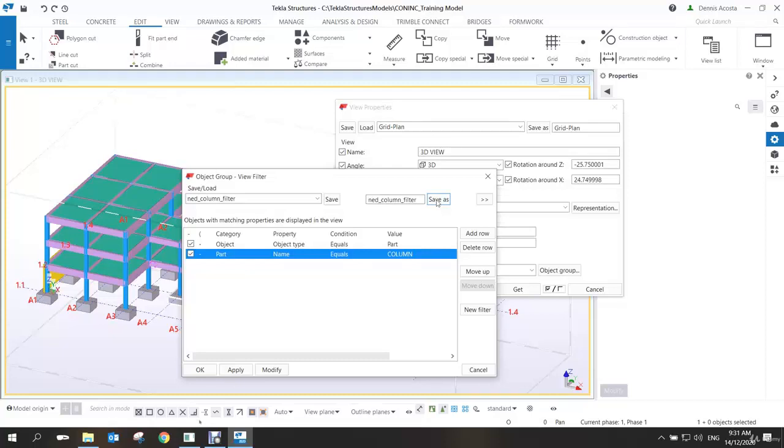So meaning that one is one of your attributes. So again, I'm going to repeat the procedure, but this time I'm not going to repeat under the object. All I need to do is to change the part name to, instead of column, I'm going to select from model and then select the beam, and then here I will save this one as beam and then save as.